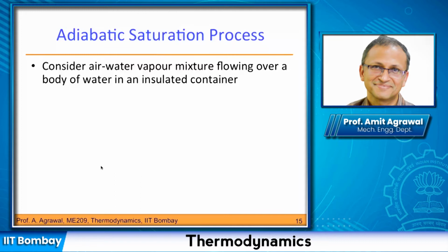By now we know that by adiabatic we mean that there is no heat transfer happening, so this becomes a much easier case. It also says it's a saturation process, which means that whatever is leaving is at saturated condition, not more and not less. Exactly at the saturated condition it is leaving.